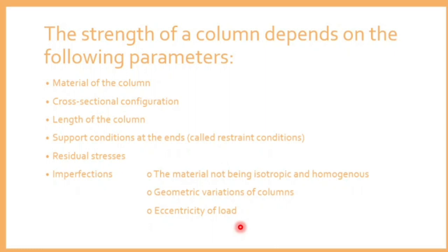So this is what I am saying here. Whenever you are designing, you can find that the stress carrying capacity of your column is not enough. At that point of time, what do you have to change? Either the length, or the cross section, or the material. Instead of 410, you can use 500 Newton per mm square, like that. Without knowing this, if you jump straight into design, in some cases the design might not come within the limit. At that point, you have to check these conditions, revise, and redo the problem. You will get a safe design.